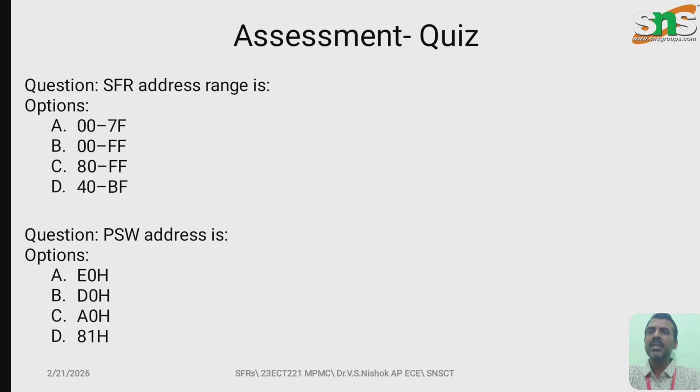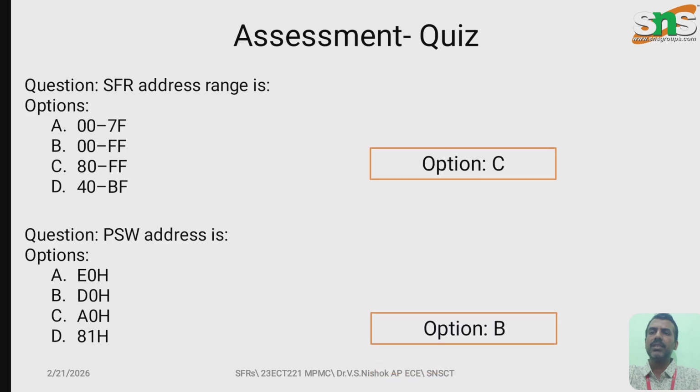The SFR address range is 80H to FFH, the upper internal RAM area. So option C is the right answer. And the PSW, program status word, address starts from D0H to D7H. So B is the right answer for the second question.